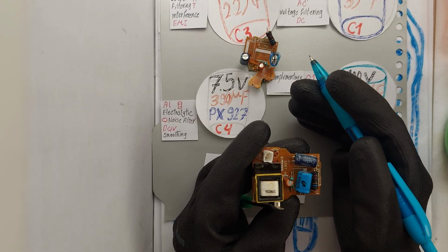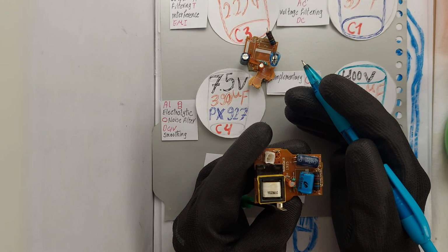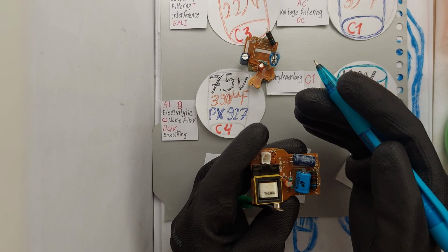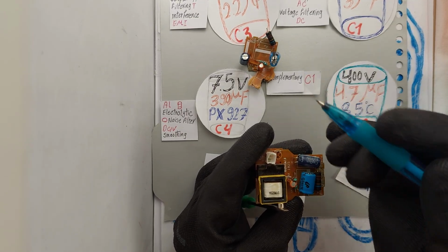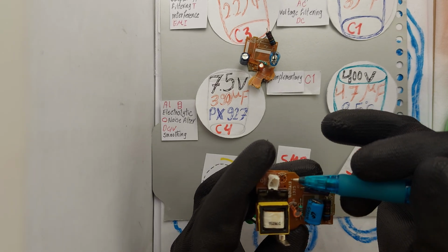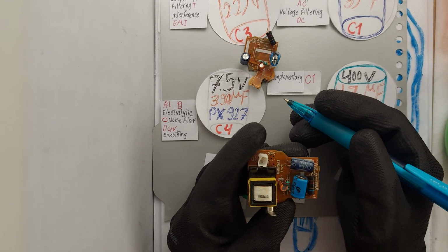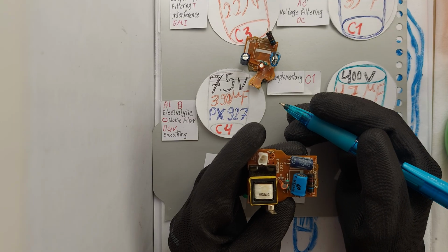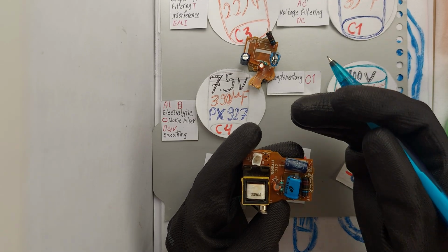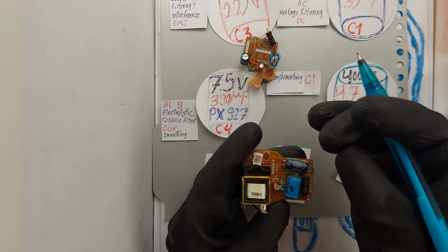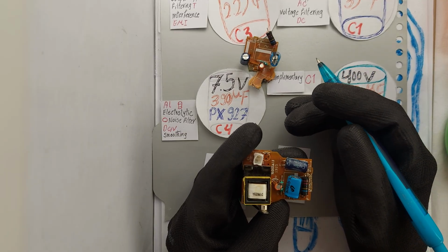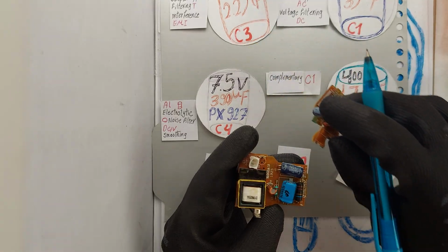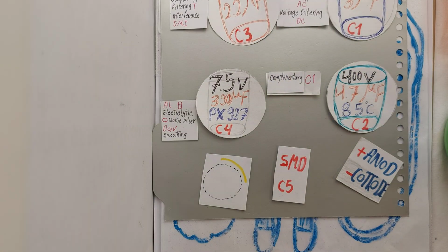So their symbols are designed to indicate orientation, as incorrect connection could damage them. And C3 and C4, located on the output side with lower voltage, 50 volt and 7.5 volt, have circular symbols. This could be due to the lower voltage or schematic drawing style, though they are typically polar capacitors in practice.